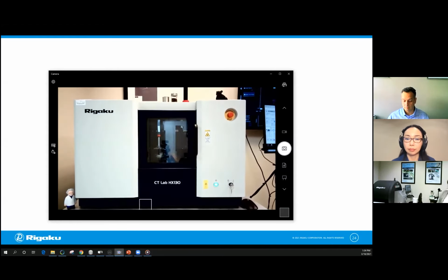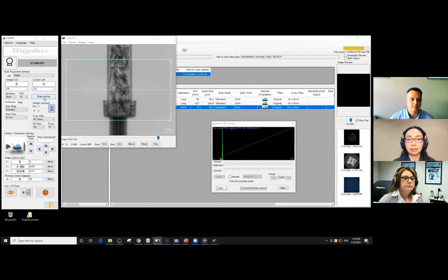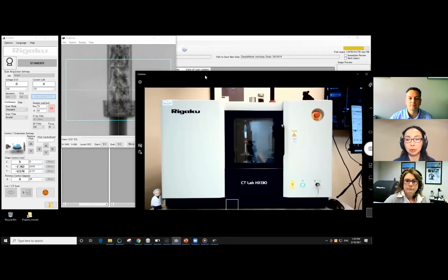And we will do a bit more of that next month when we do a high resolution X-ray CT workshop. Because the higher the resolution is, the more important that the sample doesn't move. When you have sub-micron resolution, the sample moves for 2 microns and it's completely blurred when you get the image. It is important to fix it.